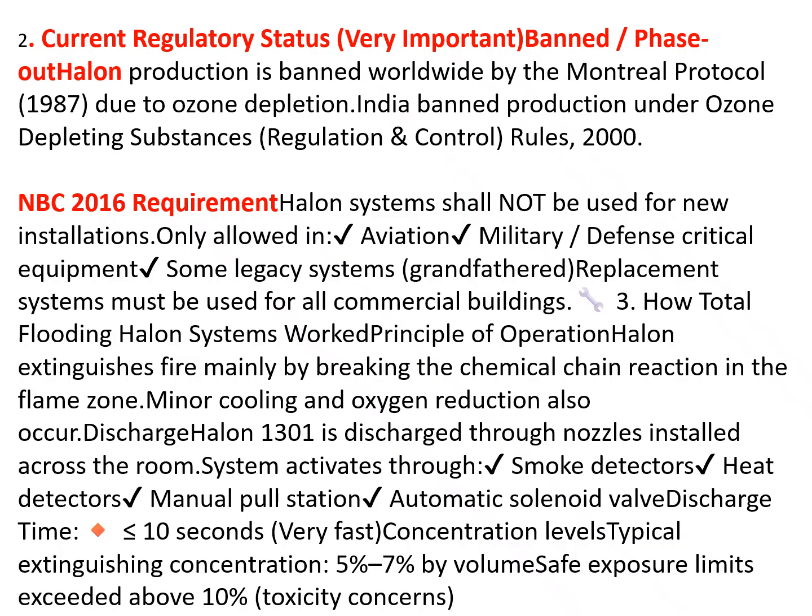System activates through smoke detectors, heat detectors, or manual pull stations, with an automatic solenoid valve. Discharge time is less than 10 seconds. Very fast. Concentration level: typical extinguishing concentration is 5 to 7% by volume. Safe exposure limit exceeded above about 10%.